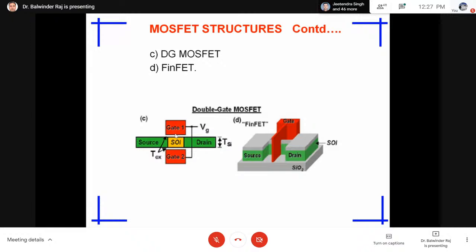In asymmetrical, we have different thicknesses of silicon dioxide, maybe one side 1 nanometer and the other side 1.4 nanometer. So why are we using different oxide thicknesses? Because, as I mentioned, of the challenges of leakage current in the bulk MOSFET, that we have to modify here.